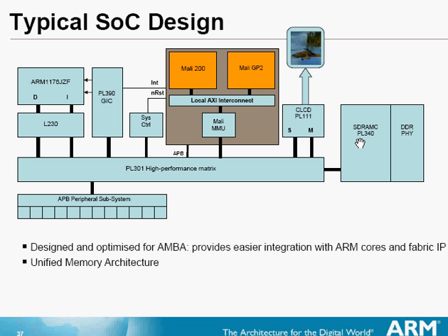So the resulting video frame is written by the Mali 200 pixel processor to main memory, where it is accessed by the color LCD controller and sent out to the LCD. The controller in this case is another ARM PrimeCell called PL111. See, this one is an ARM cell, this one is an ARM cell, this one is an ARM cell, and this whole system. So this is a typical SoC design, showing where ARM products fit in and how they provide interfaces and so on.